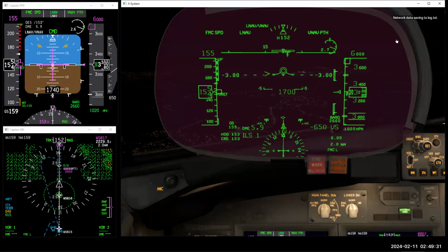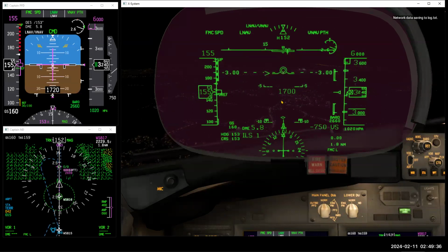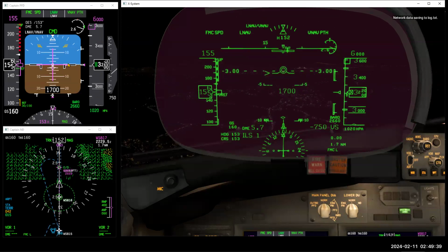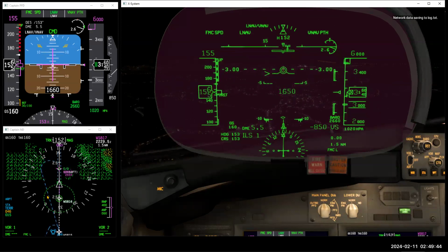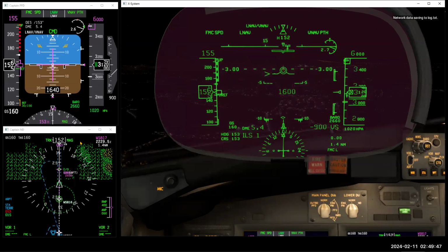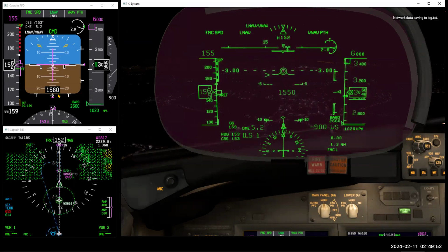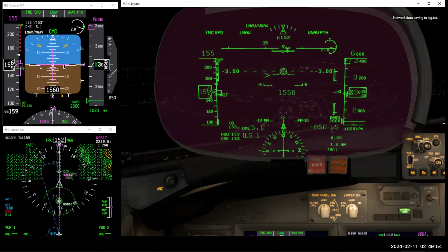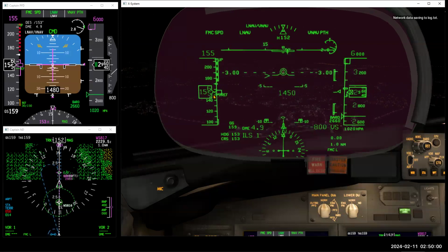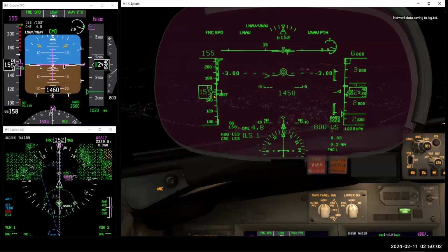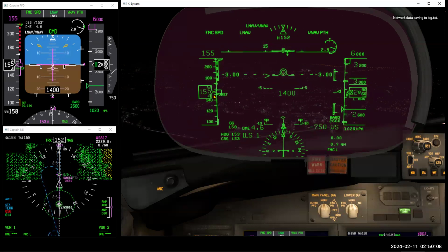All right, we are on the move, and the picture we have on the primary flight display is exactly what we're looking for. Picture on the nav display also, rate of descent is good. Radio altimeter is good for where we are. No corrections on the baro altimeter because the temperature is such that we don't have to make corrections. The HUD is giving us a good picture of what we are expecting, and we are coming up to minimums.